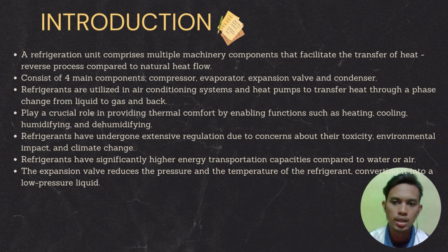They play a crucial role in providing thermal comfort by enabling functions such as heating, cooling, humidifying, and dehumidifying. Refrigerants have undergone extensive regulation due to concerns about their toxicity, environmental impact, and climate change. Next, refrigerants have significantly higher energy transportation capacities compared to water or air. The expansion valve reduces the pressure and the temperature of the refrigerant, converting it into a low pressure liquid.